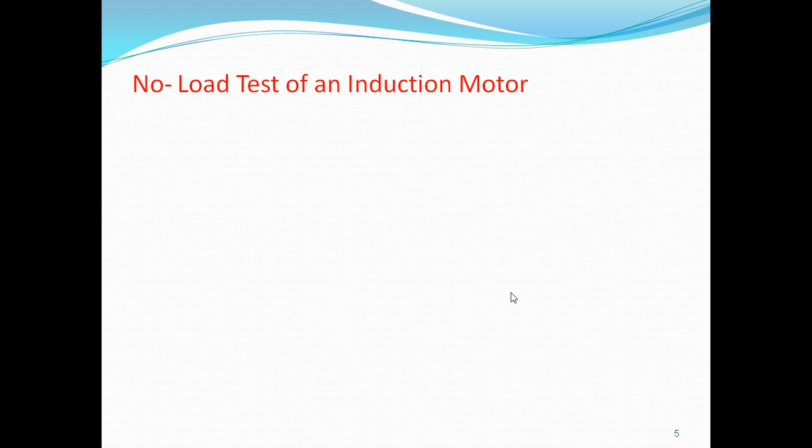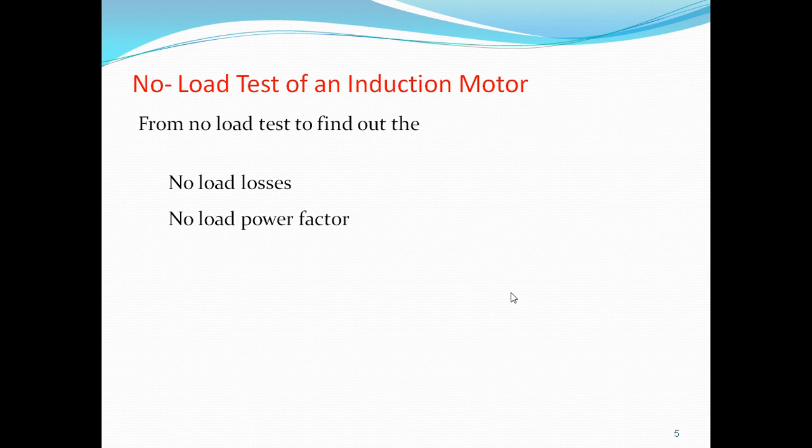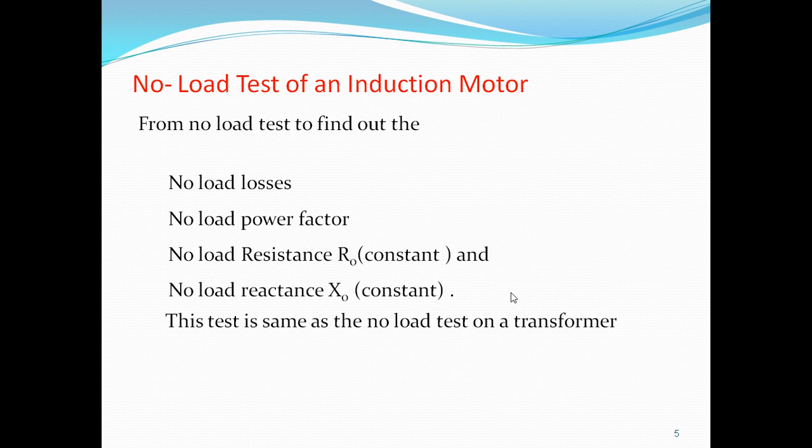If you consider no load test of an induction motor, the name itself says we are not applying any load on the induction motor. From no load test, we can find out no load losses and no load power factor, and no load resistance R naught and no load reactance X naught.